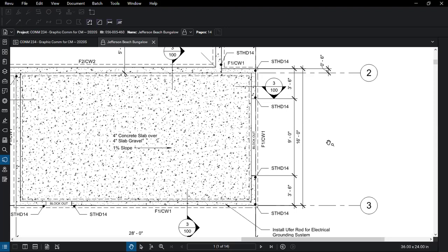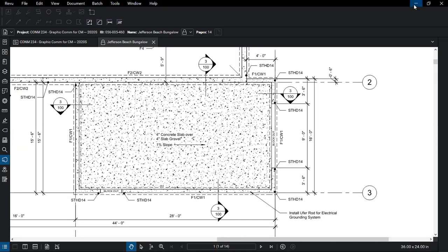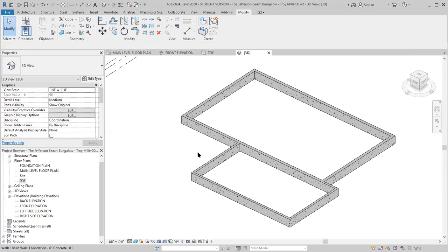So essentially, the purpose of this blockout is we're going to create a little bulkhead, if you will, that will prevent the concrete when it's poured from going into that area. It'll basically push the top of the concrete wall down, so your concrete slab can go out over that foundation wall, which will allow either foot traffic in your passage door or vehicular traffic through your overhead door. All right, so let me just really quickly show you how to create that.